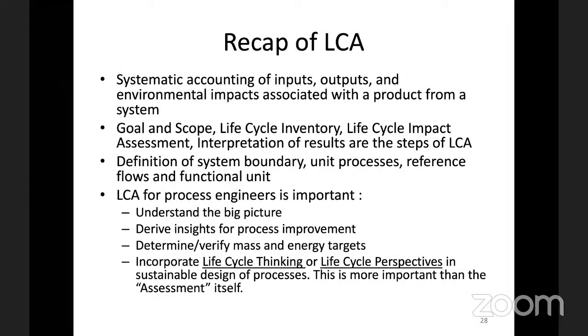And life cycle assessment for process engineers is important to understand the big picture, to derive insights for process improvement, to determine and verify mass and energy targets, and to incorporate, and this is according to me the most important thing, life cycle thinking or life cycle perspectives in the sustainable design of processes. This is more important than doing the assessment itself. So you have to develop an understanding or appreciation of life cycle thinking or life cycle perspectives in order to have sustainable design of a process.